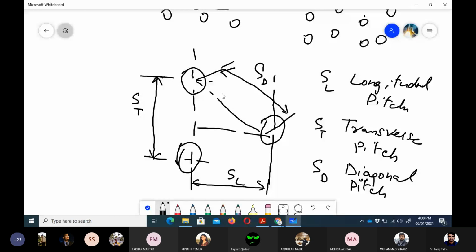I just gave you the introduction of the tube bank, because tube banks are very much present in all the heat exchangers we encounter in practical applications like condensers, evaporators, boilers. In all of these, because of the limitation of space, we have to have bends in the tubes so that we can accommodate more surface area of the tube in a limited volume. That's why we need to do analysis for the flow over the tube. We are talking about external flow at the moment, right? For the internal flow, there would be chapter number 8.